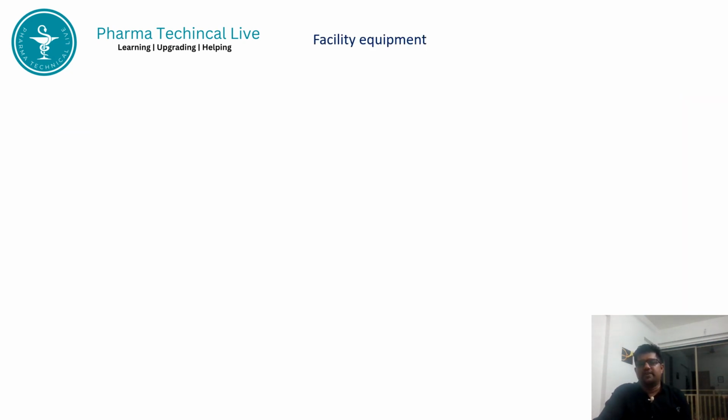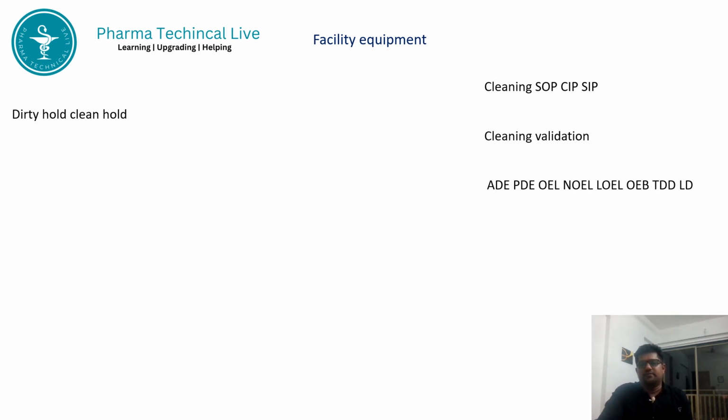Then we will move to the next source of contamination, that is the facility and equipment. For facility or equipment, we should have validated cleaning procedures like CIP, cleaning in place, and sterilization in place. The effectiveness of cleaning should be demonstrated through cleaning validation, and it's a big topic. I will come with another session of videos on how to deal with cleaning validation, like permitted daily dose, lethal dose, observed effect level, and occupational exposure bands.